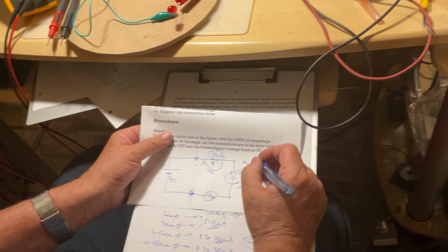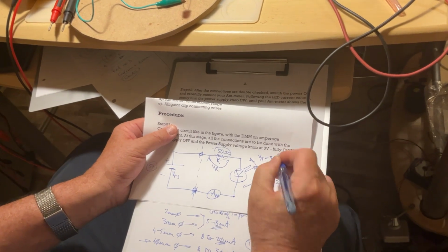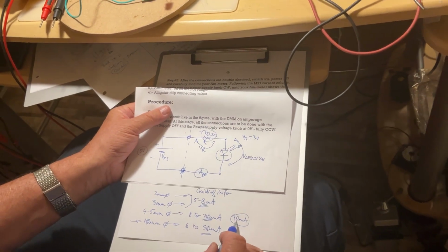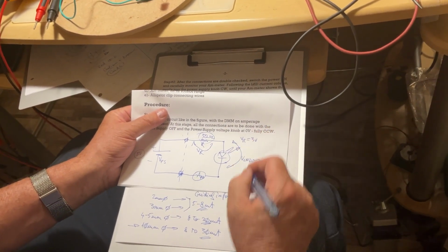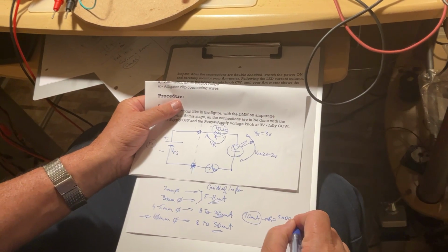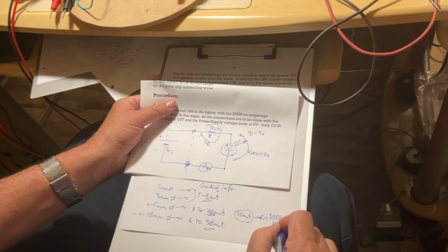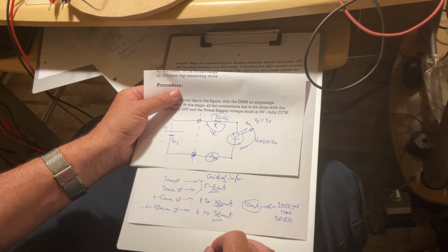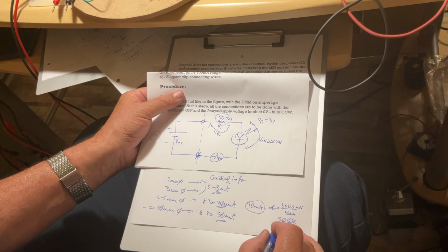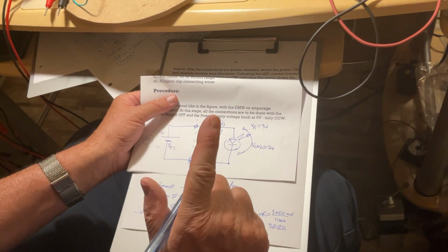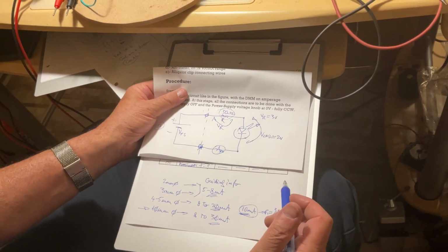Now, when we have 5 volts for the power supply and 2 volts across the LED, the voltage across the resistor becomes 3 volts. So, for the resistor here to pass 10 milliamps, what resistor should be there? The new resistor should be 3 volts, which is 3000 millivolts, divided by 10 milliamps, approximately 300 ohms. So anything around 300 ohms is going to be good if you want the current to be maintained at 10 milliamps. That's how you calculate the resistor, but there's something more, and this is where the dissipating power becomes important.